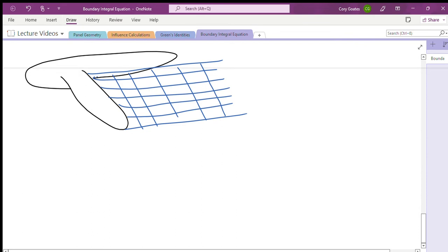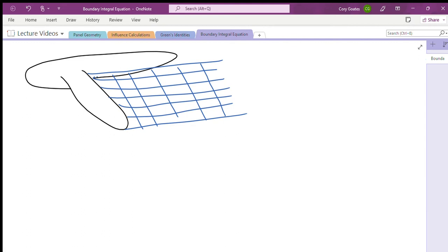the wake surface. Because if you'll remember, like we said, doublet panels induce a jump in velocity potential. And so when we've put in these panels here, we've introduced a jump in the velocity potential across that wake surface. And so it's a discontinuity, and we have to actually split the fluid region on the wake surface.